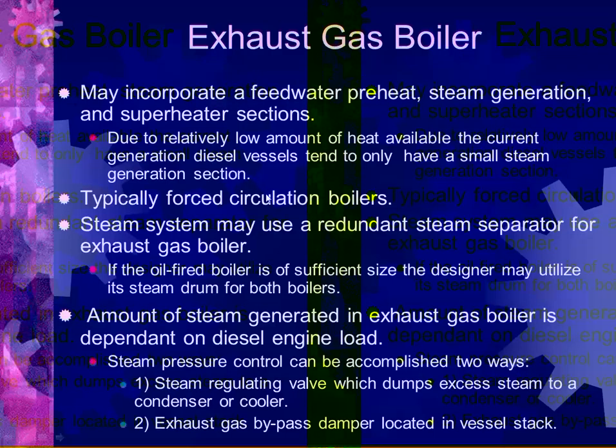So again, you will not typically find forced circulation like we have on the Bear, except for these exhaust gas boilers. So typically, most ships, container ships, have only heating loads. What you're going to have is an oil-fired boiler of some type, and typically that's going to be a fire tube type, producing steam in port.